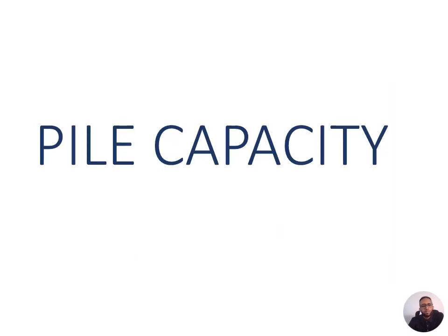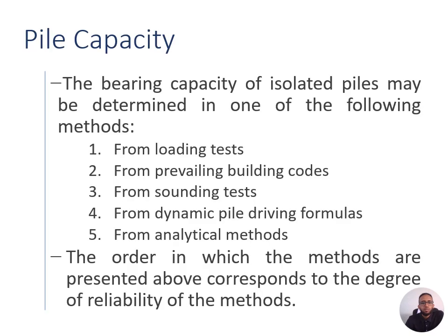The third part, which is pile capacity. So the bearing capacity of pile can be determined using different approaches and methods. And as you can see here, we have 5 listed methods. From this, the most reliable method is conducted on a full-scale loading test on the piles.